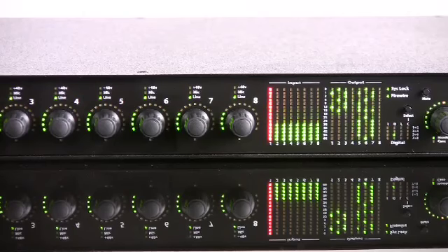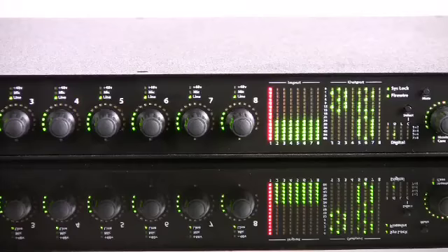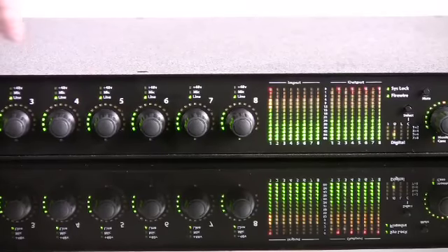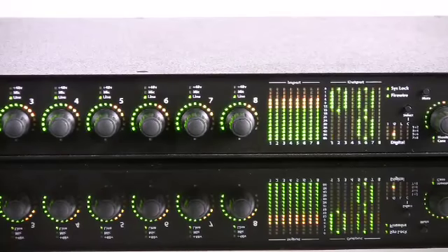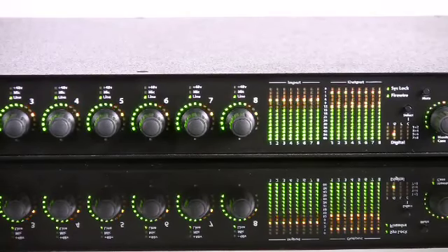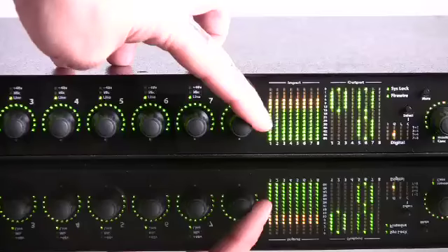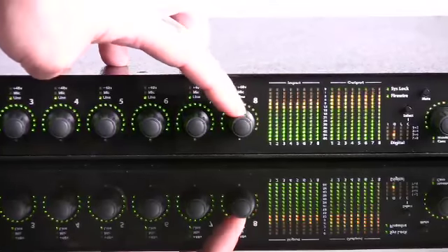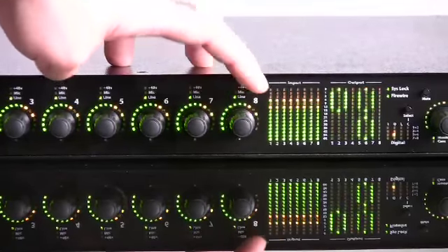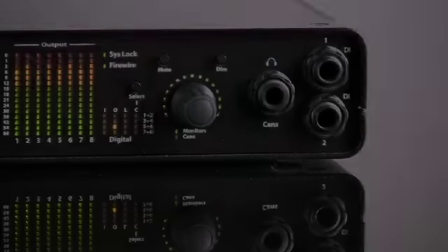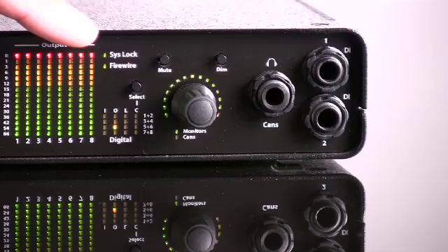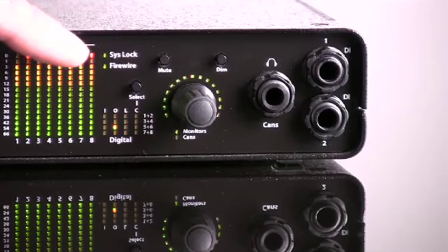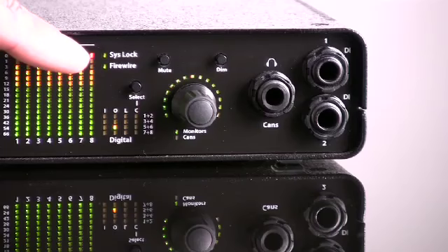There's another user-selectable meter mode. With the I/O trim in the input position, press on encoders 1 and 8 simultaneously. You can now see the channel's metering directly around its encoder. By holding the I/O trim button in and turning encoder 8, you can change the brightness of the front panel. On the right of the front panel, we have the syslock indicator to show that the box has a valid clock source, and the FireWire indicator, which shows that the box is connected to a computer.